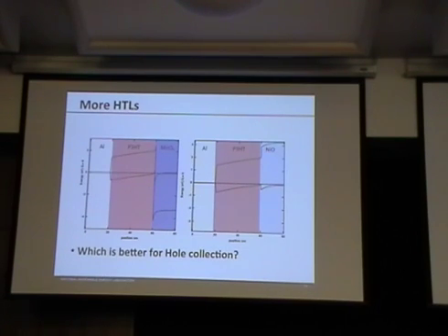Now, we may hide a lot of those energetics in things like surface states. So let's talk about that. What happens if I have a bunch of defect states here? What are they really going to do? Or what kinds of things can they do? They can do recombination. They can cause charge carriers near that interface to fall together. Okay, that's one thing. What else can they do?